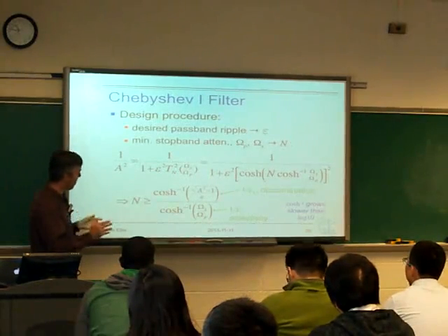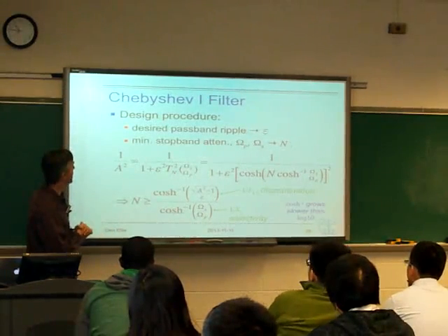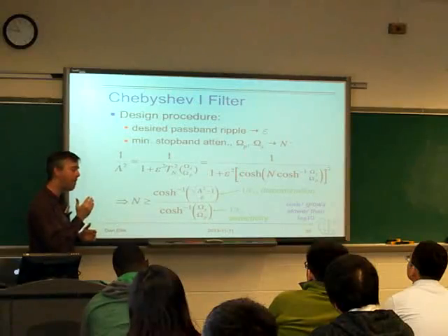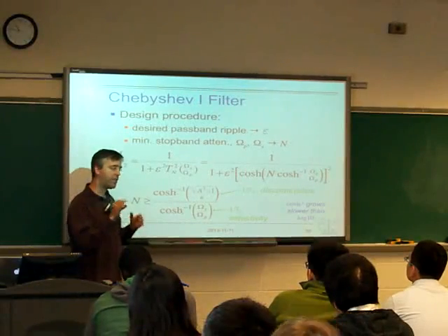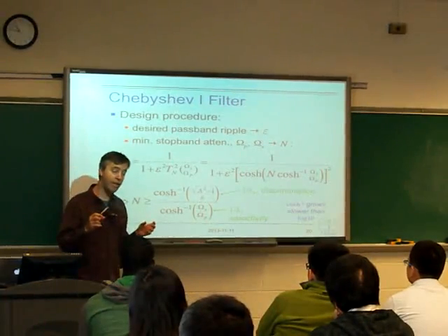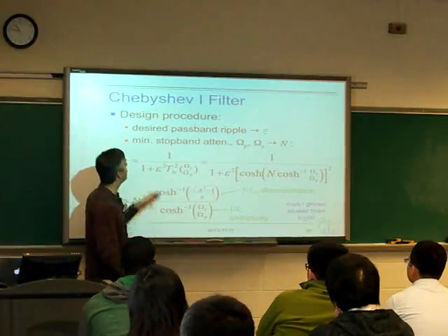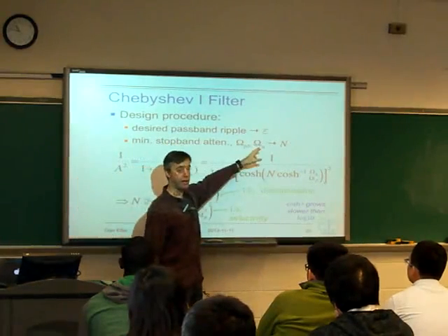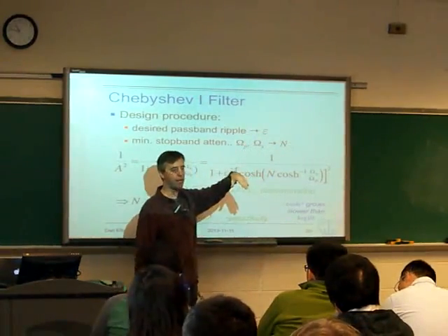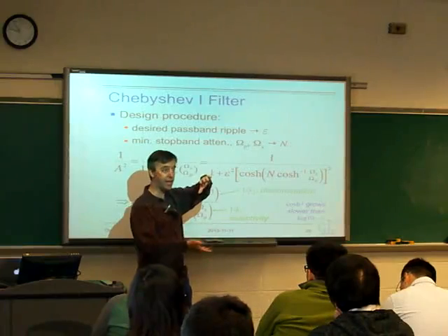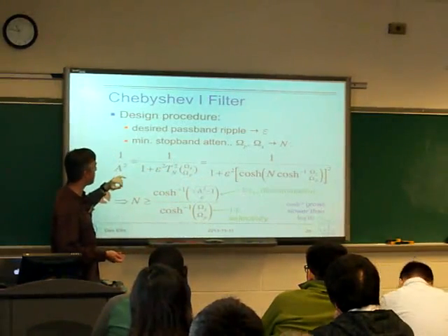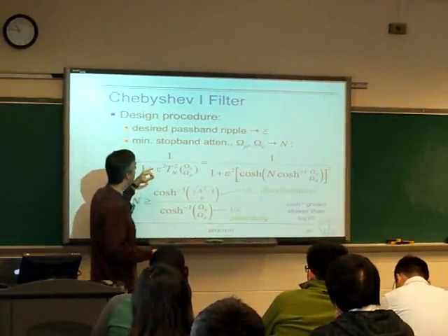Okay, so given the existence of these things, how do we actually go about building a Chebyshev 1 filter? Well, basically, if the specification says, okay, I want to make this low-pass filter, here's the amount of ripple we can tolerate in the passband, then that passband ripple gives us epsilon, right? Epsilon basically says that 1 over 1 plus epsilon squared is going to be the smallest squared gain in the passband, so we set that.